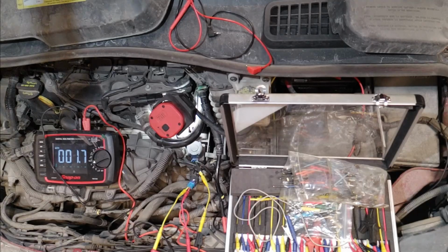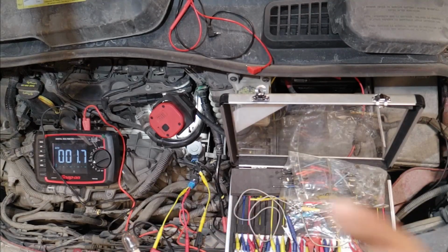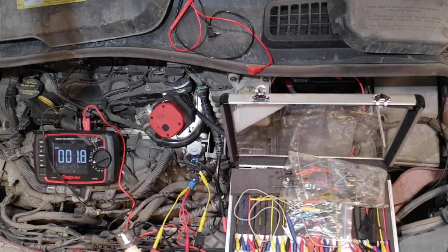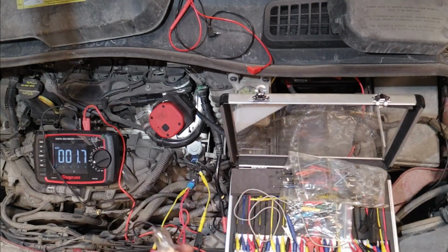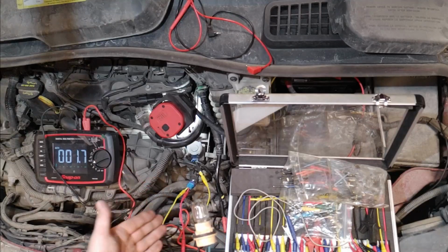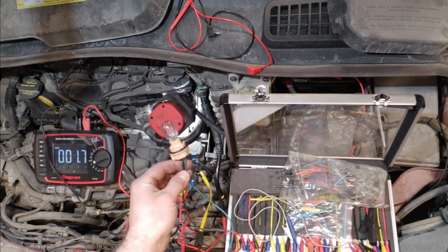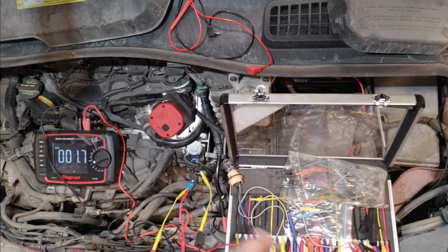So the first thing we're gonna do is that I'm gonna start the car. Now, the way that I'm thinking that this is gonna work is that because the engine is relatively cold, the PCM is gonna control this valve. Now, when the PCM tries to control this valve, since I have this light installed in place of the valve, this light should light. Now, if this light lights, that means that my control from my PCM, my ground, my power, all that is good. And the issue is gonna end up being my valve. So let's go and start it up, and we'll see what's gonna happen.